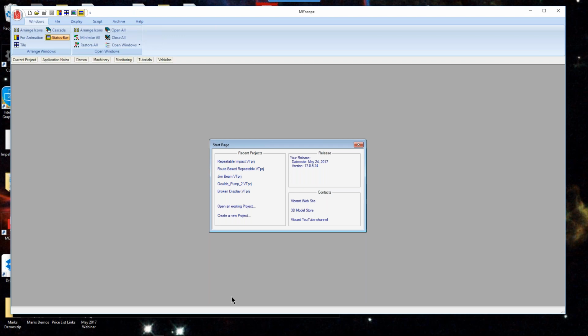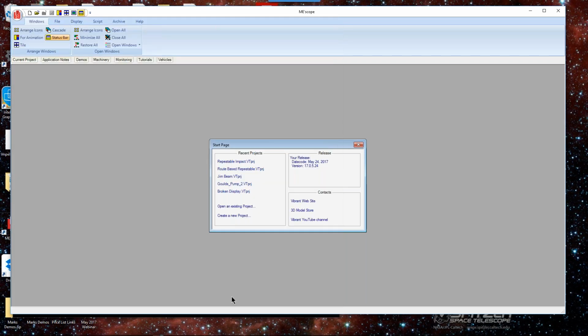It's very much like the Modal Assurance Criterion, or the MAC, and both of these measures are correlation coefficients between two vectors of data. So if I have two mode shapes, if I have two ODSs, if I have two sets of time or frequency data, I can use these correlation coefficients to tell whether they're the same or different.